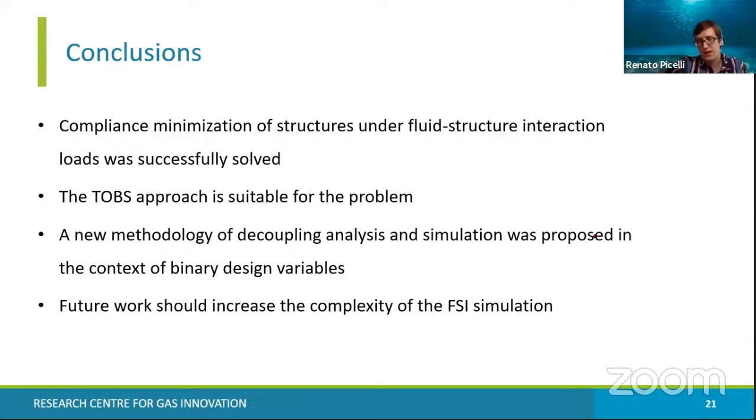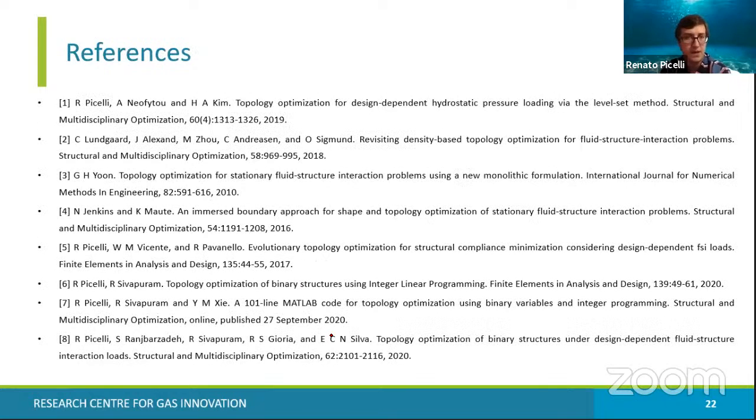And as a conclusion, I bring that compliance minimization of structures under fluid structure interaction loads was successfully solved. The TOBS approach in the standard form is suitable for the problem. It's at least a competitive candidate because of its binary design variables and mathematical programming. And we bring in this paper a new recipe of decoupling analysis and simulation in the context of binary design variables and FSI. Future work should increase the complexity of the FSI simulation or maybe extend this to other physics. These are the references I mentioned during the presentation.